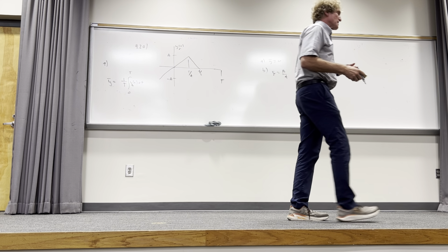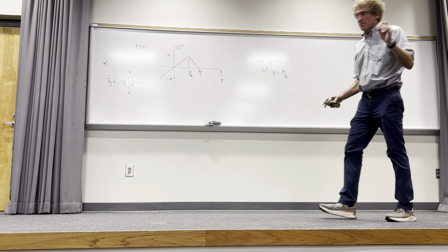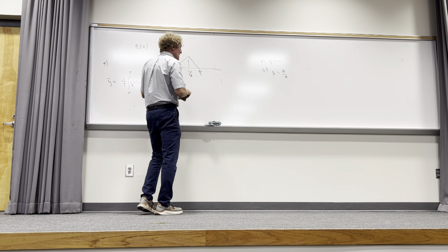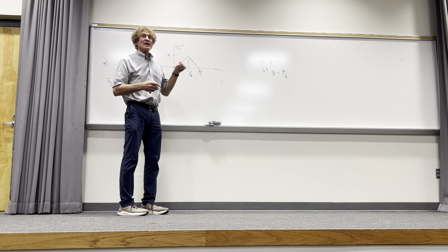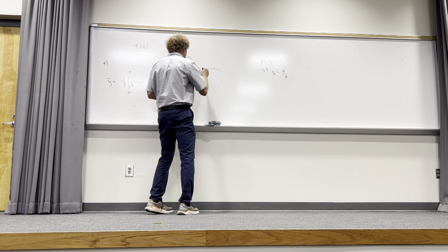The final part of this, and I wish he would have drawn these waveforms. What does it say? If the wave is full wave rectified, plot the voltage versus time, calculate the DC value. Now this, just listen to me. Full wave means the entire waveform is going to be in the positive sector. The negative going parts will become positive. Y'all with me? And it looks like this.